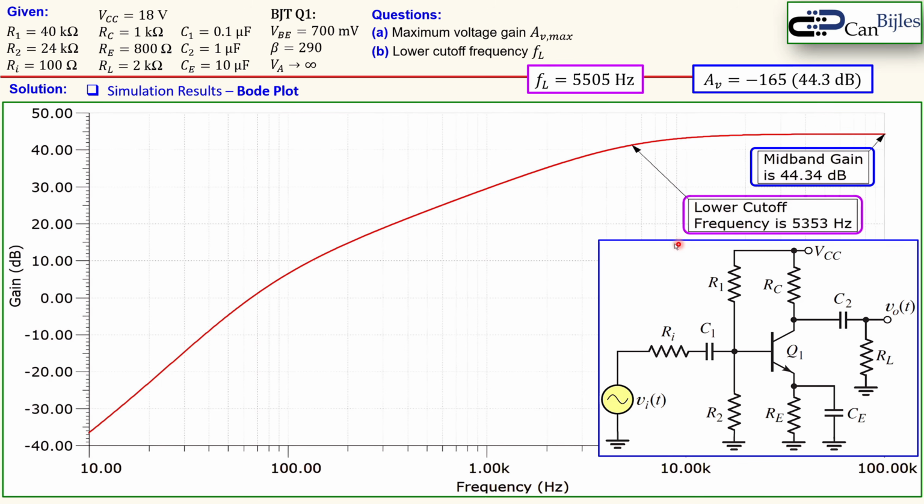Again, why? Because we use an approximation, which is of course not always perfectly valid, so maybe 95% or 80% of the time it is correct. In this case we see a small error here. So it is still very nice with this confirmation in our calculations. So we can say we have achieved our goal, and we have verified our calculations in the SPICE simulations using the Bode plot here.